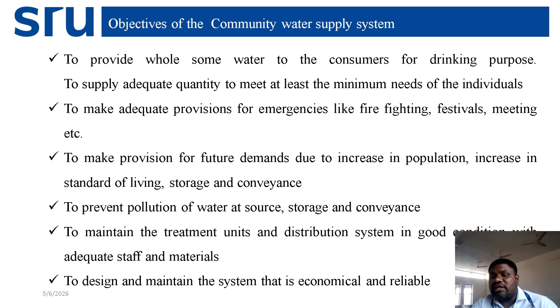Other than drinking purposes, there are several factors that can influence demand. Maybe firefighting during fire accidents requires a large amount of water. And maybe during festival time the consumption of water will be very high. And maybe some quantity of water may be lost, depletion also will happen. So for that we need to provide some extra.